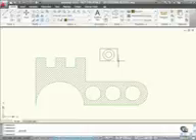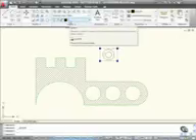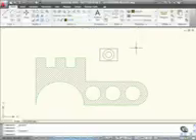Now, have a look at the objects. They're not on the current layer, the block layer. What they're actually on, if you click on it, they're on layer 0. Now, there's a reason for that. If you create a block on layer 0, it will automatically adopt the current drafting layer when you insert the block into the drawing. So let's have a look at that now.